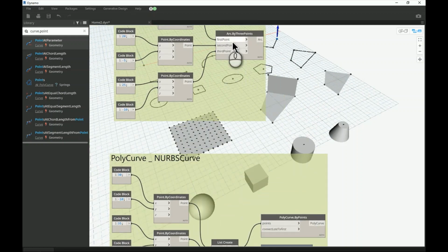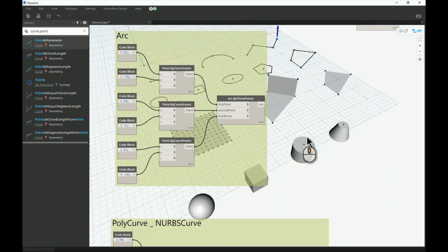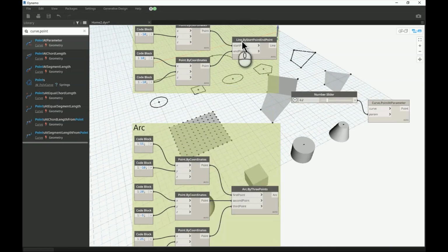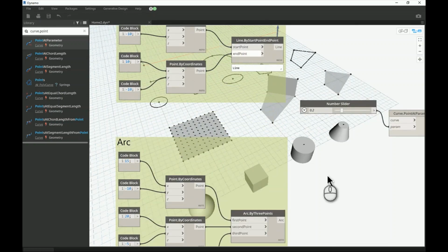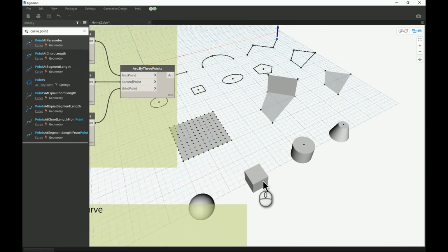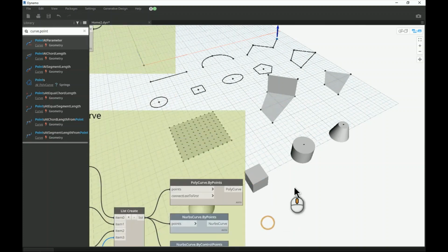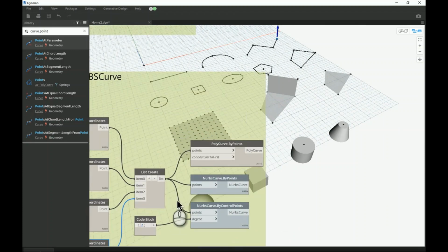Here it's a first point, so just 1, and you know the line here, start point. Be careful with the singular and plural conditions in Dynamo. I know, pain, I know. Because here it's expecting a point, so you have to create a list. Just use List.Create, keep pushing this plus, and have an item for each point you want. Now you have points, and you send them to the points input, and you get your polyline.